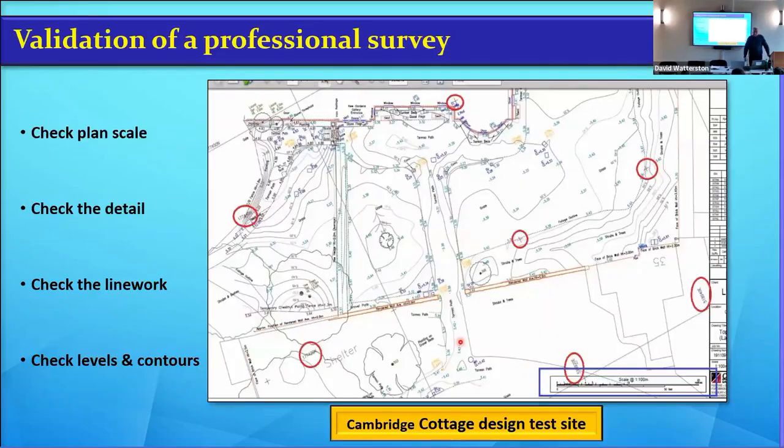How do we check the plan? This is what I was going on about. The grid crosses. This is the grid that surveyors might ask you about. What grid interval do you want? And this is probably 10-metre intervals, right? 10 metres from there to there, 10 metres from there to there. The Ordnance Survey are probably 20-metre intervals there, or 50. So that is your grid interval. And then the level grid is probably only about 2 or 3 metres. So I've gridded loads of them because it's a flat area. You can tell by the contours there's not a lot happening.